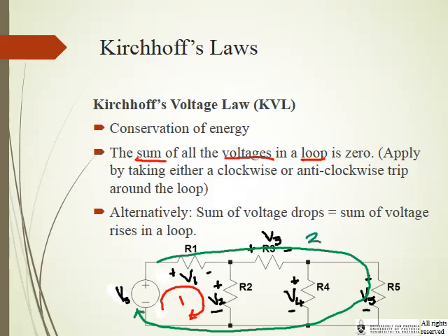Right, so if we write down at the top Kirchhoff's voltage loop law for loop number 1. We start at the source. Very important, what direction did we choose? I chose clockwise, and now you have to write the polarity in which the loop goes in.